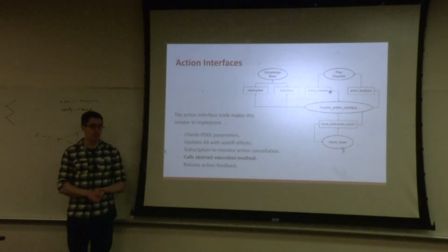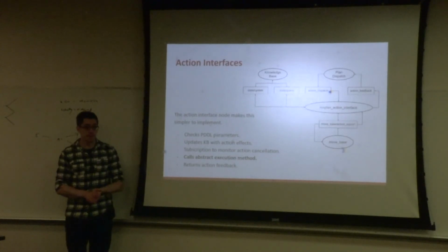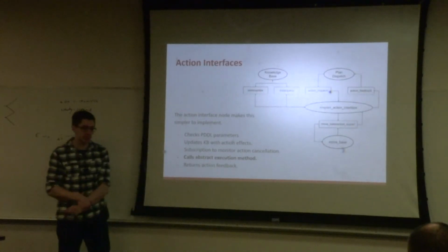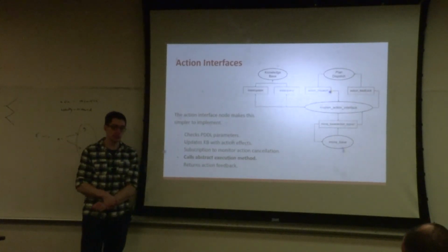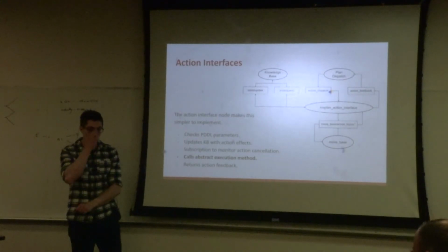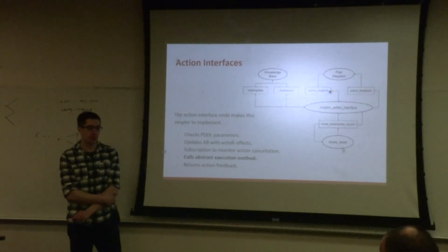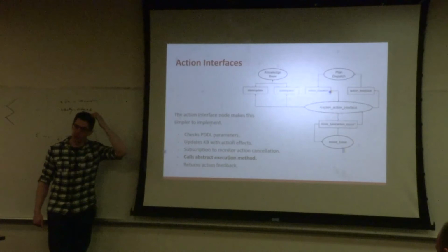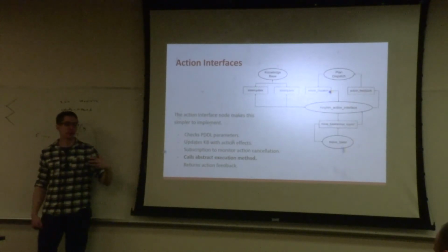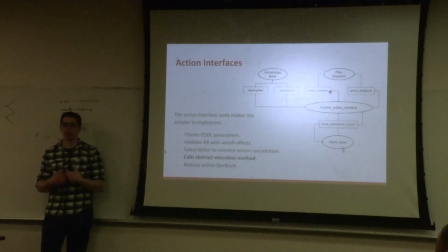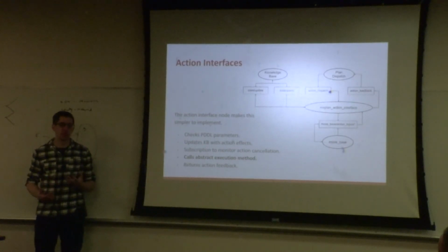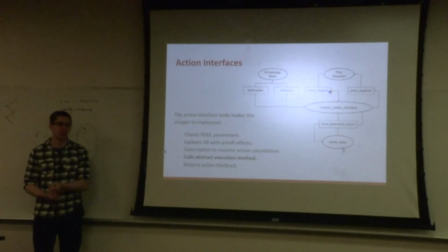So there are these parallel checks happening. Even if I cross the threshold to get to waypoint 1 or waypoint 0, and the knowledge base gets updated, if MoveBase fails before I get all the way, the action will still fail. And in our implementation, the plan execution will return true or false if the plan was successful or not. There are actually a number of reasons the plan can fail. One of them is if any action fails, the plan reports failure.